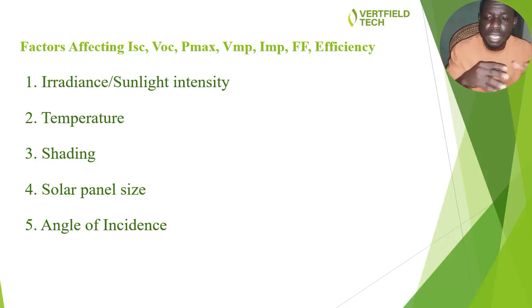Now, in solar system installations, when you go for site survey, you are also to consider the place of installation for your solar panels. And at no point in time should you install your solar panels under a tree or where you are having shades over it, or where a taller building will cast shadow on your solar panels. On no account should that ever happen, because once a side of the solar panel is shaded, the efficiency of that solar panel has been reduced.